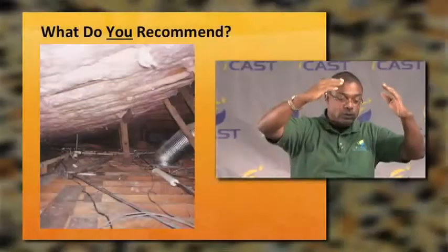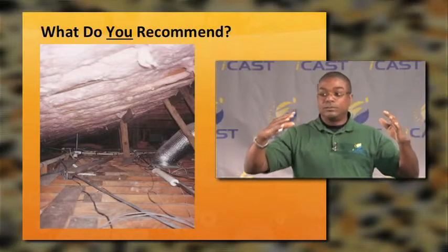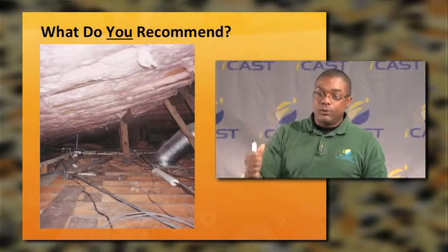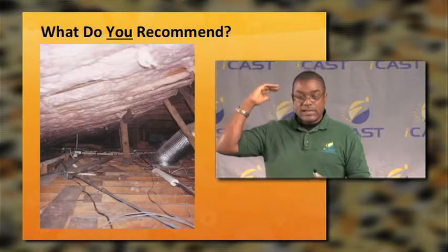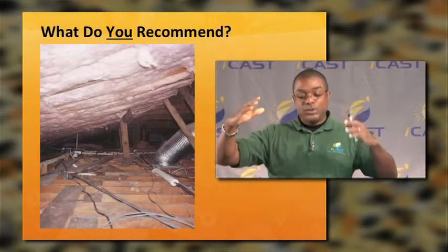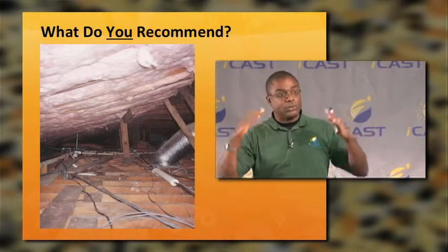There's a debate that goes on with how to insulate and air seal attic space. One rule of thinking is found here in this slide, which is insulate at the roof line. So what do you think? Is it a good idea to insulate at the roof line? Well, the most important thing with attic insulation is to make sure that you have a nice tight air seal between conditioned space and unconditioned space, and you have a solid thermal barrier.